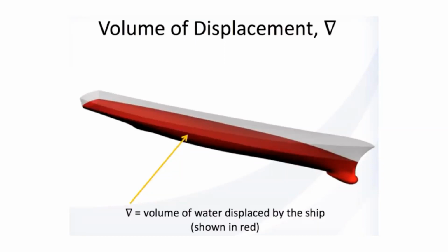With the mass properties, we see how much buoyant force that design has. We compare it to what weight was on the system, and we figured out how much negative or positive buoyancy we had and what we needed to do to accomplish our goals. It's a little bit tedious, but it can be done.